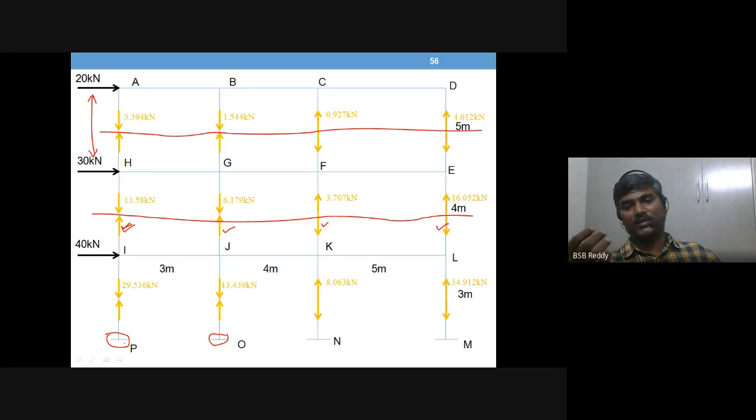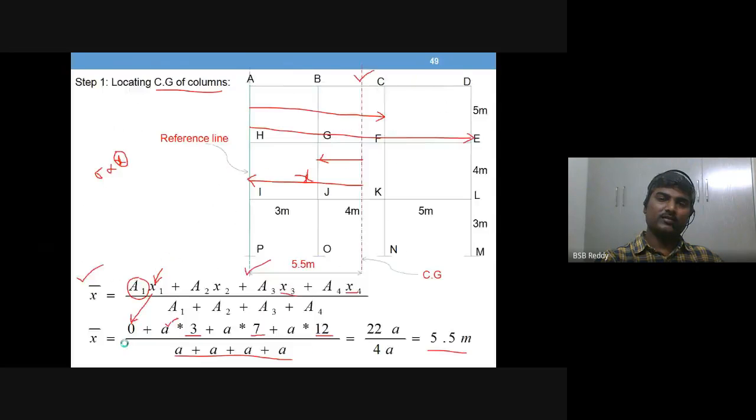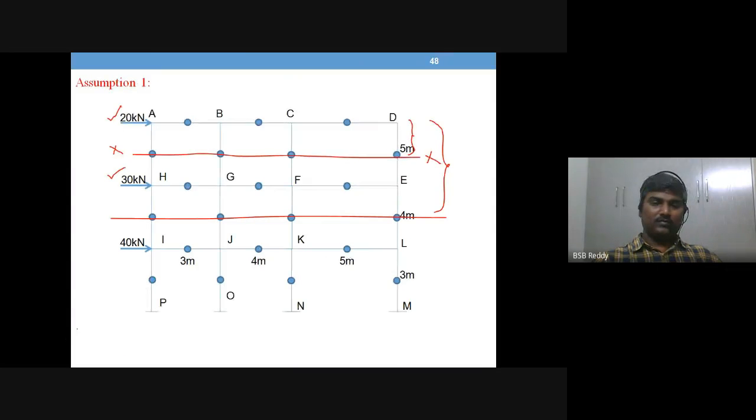So a bit more is to be done. Equations are to be generated. That's why we are comfortable with the portion above the section. Okay, right. Now to work out the first story, bottom story. Pass a section through the middle of the bottommost story.